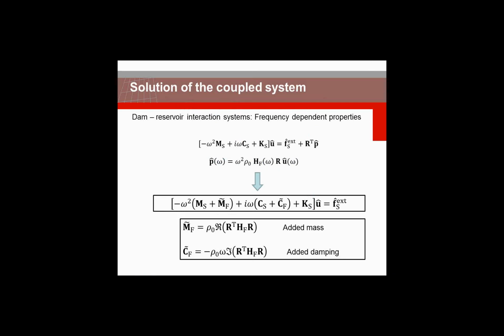So we have to understand and keep in mind that this kind of solution allows us to understand that the fluid structure interaction functions in a way that introduces mass and introduces damping to the system, to the dam equation of motion, right?